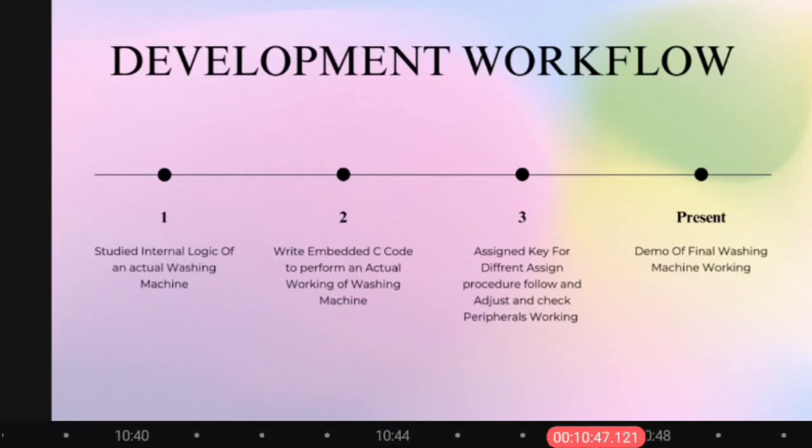If the user presses switch 5, then it will start the program and display the selected program and shows the time. The LCD displays the particular program and time in minutes and seconds. When the machine starts to run, at the same time the fan rotates, and the board will be showing the remaining time to complete on the LCD display. The program also shows whether the clothes are washing, rinsing, or spinning. The LCD displays 5 to start and 6 to pause.